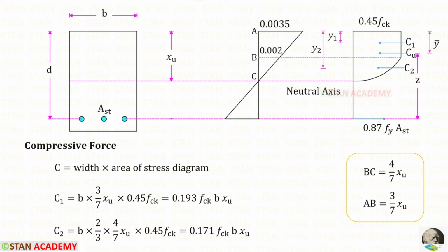Now we are going to find the compressive force that will be within the area of the stress diagram. In the stress diagram, there are two parts. First, the rectangle. Let us keep this as number 1, and then the parabola. Let us keep this as number 2.